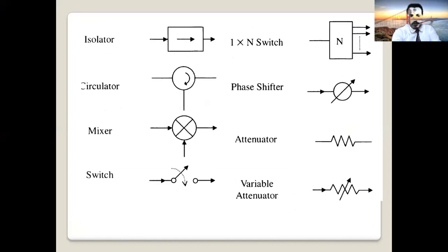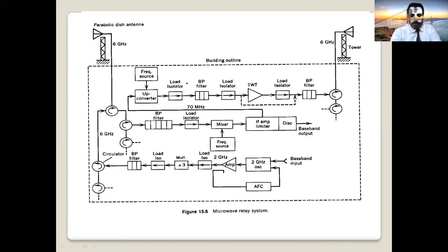So the symbol you see here is a circulator. The symbol is what? This is clockwise because of the direction of the arrow. When you see microwave systems here, you can find many circulators. Here, 2 circulators. Are they clockwise or anti-clockwise? They are clockwise circulators. This is the direction. How many ports? Port 1, port 2, go to what? The antenna. Port 3 here.